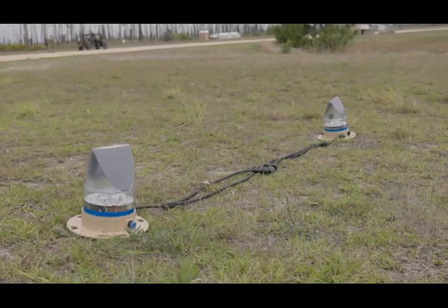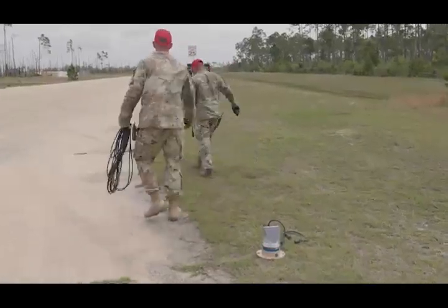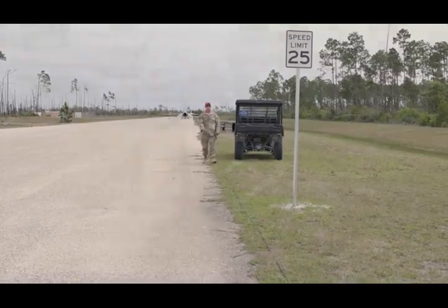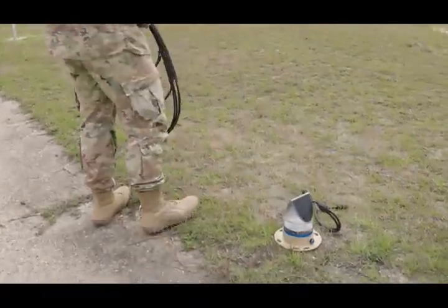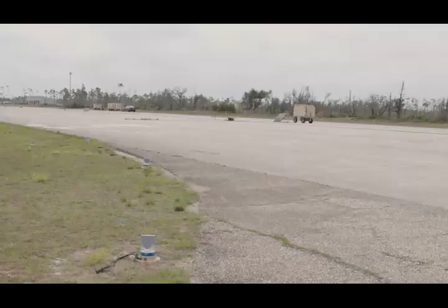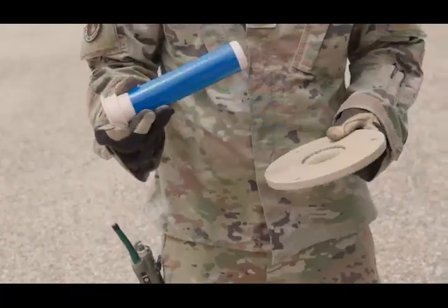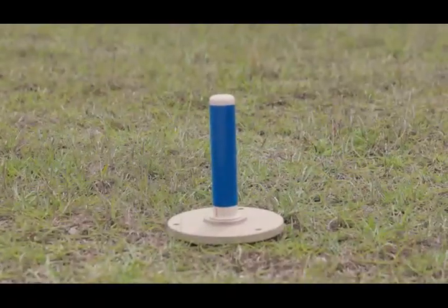On straight sections, install taxiway lights every 50 feet, and no more than 25 feet apart on curves. Use reflectors away from the runway to free up lights for other taxiways.